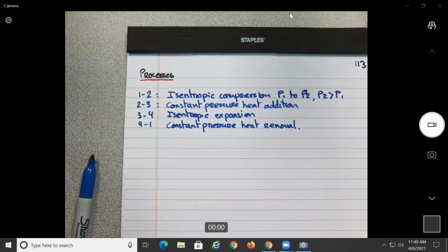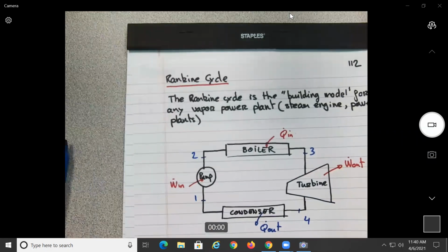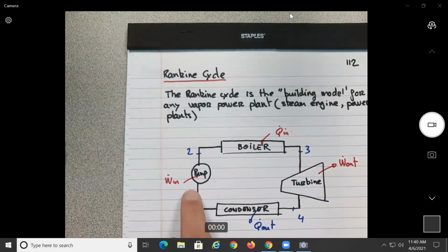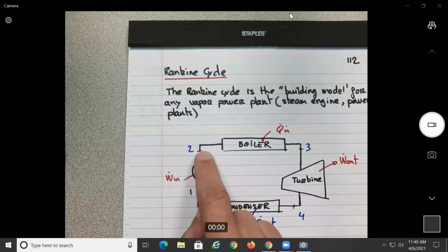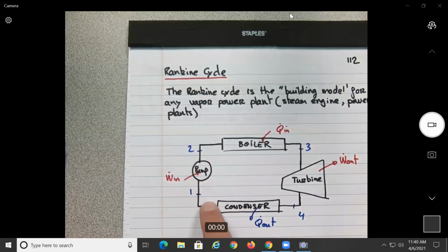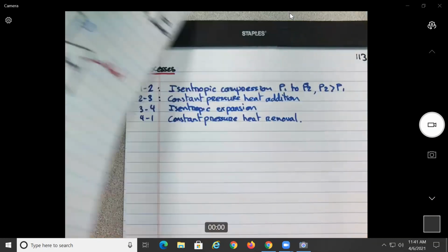Okay, so hopefully by now we have done enough, but what should be the value of the power in at the pump? If we take the pump as the control volume, there is no heat addition, so the power should be equal to what? M dot (H2 minus H1), no? Let's do the first one, but I'm not going to do it for the other ones.